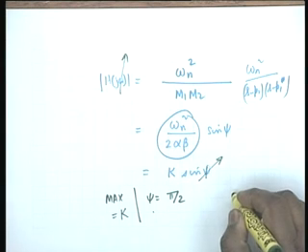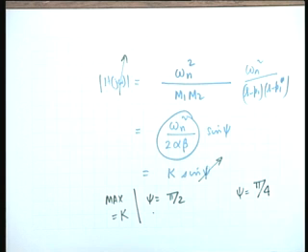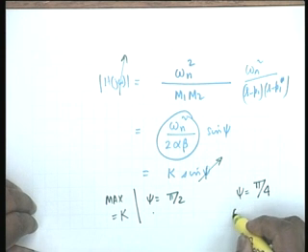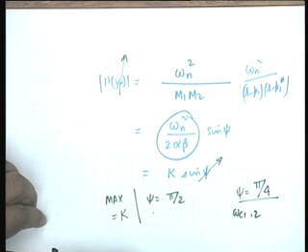We can also do this analytically, but we shall lose sight of the physical picture as to what is happening, and geometry is much more beautiful than pages of algebra. I find this very intriguing and interesting. So, all that we have to find out now is the values of omega at which the angle psi becomes equal to pi by 4. If we want to find the half power frequencies, all that we have to find is the frequencies omega c1 and omega c2 at which psi is equal to pi by 4.